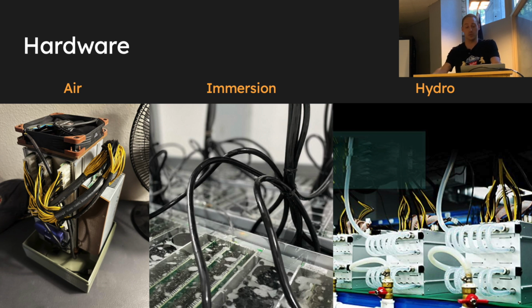The whole machine is submerged in fluid. It's also very heavy fluid. It's thick. It has what's called a high specific heat capacity. It's viscous. The specific heat capacity means it takes a lot of energy just to change the temperature of that fluid. So it's like trying to pick up a heavy weight, it takes more energy, right? Same thing there, and it's conductive, so it has a higher conductivity than air.